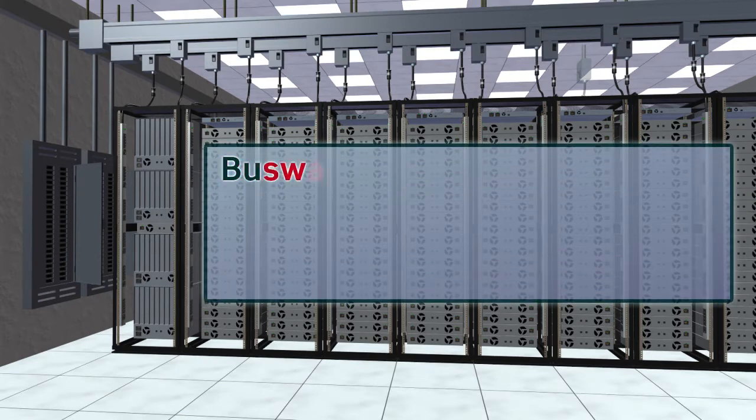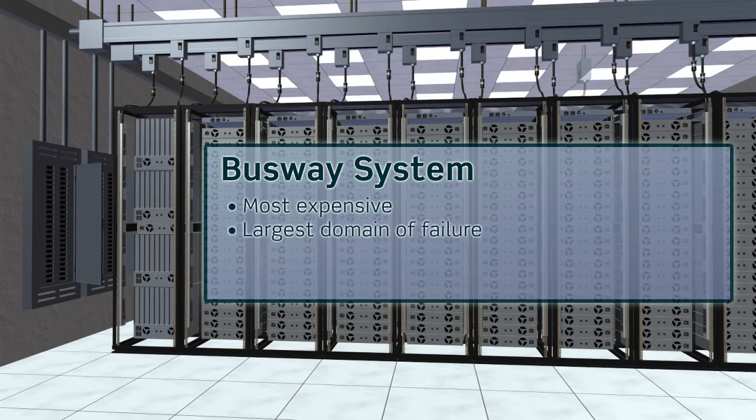Power distribution with a busway system was derived from factory floor electrical distribution practices, where you are moving carts and forklifts on smooth concrete floors. It usually is placed overhead and installed on site. It is the most expensive method to buy and install and has the largest domain of failure. It is also difficult and expensive to upgrade the power capacity of a busway system after installation. Once installed, changes to it are made by adding, moving, or removing busway tap boxes.